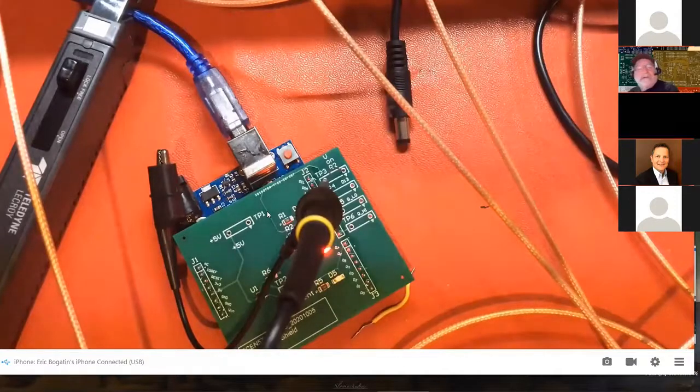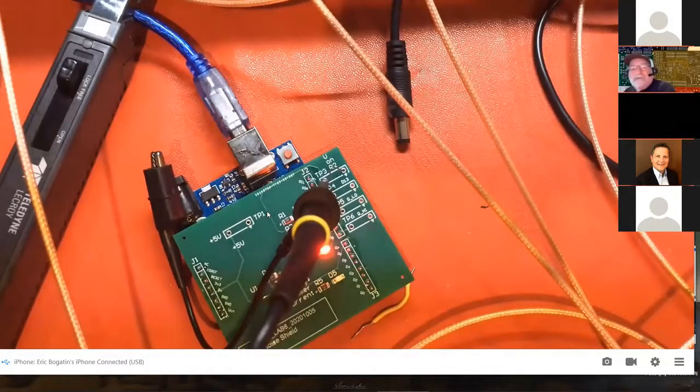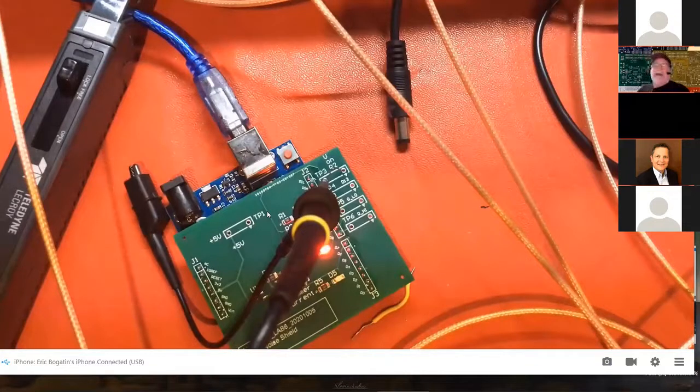That's why it's always a good habit to avoid the long floppy leads, and that's why you want to think about designing your boards, especially in bring up and test, with these special little pads in order to be able to use the little spring tips. You need a return location in close proximity to the signal in order to do that probing.